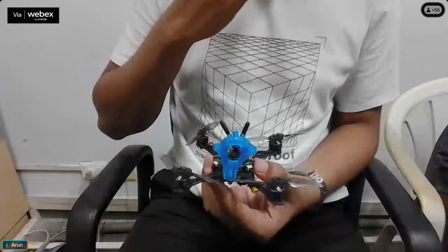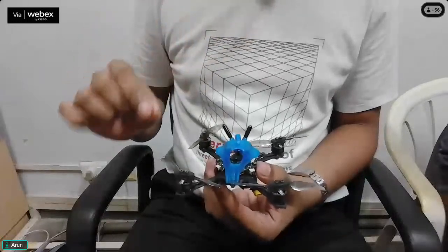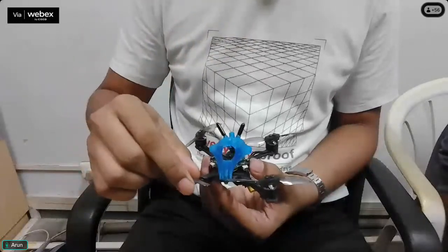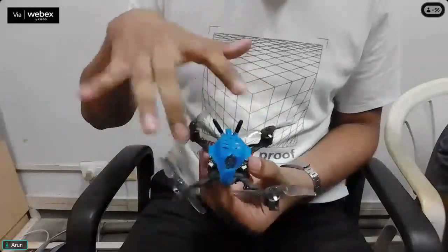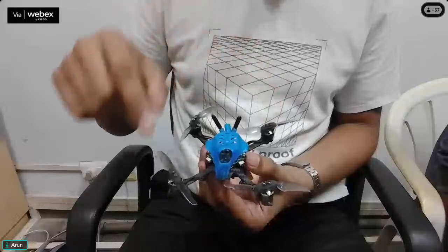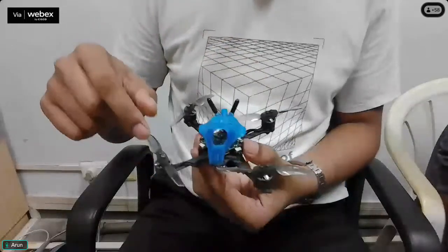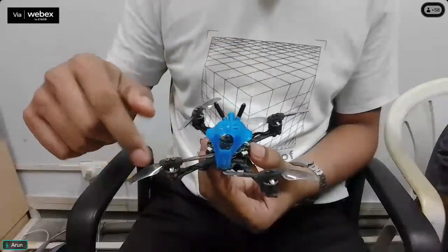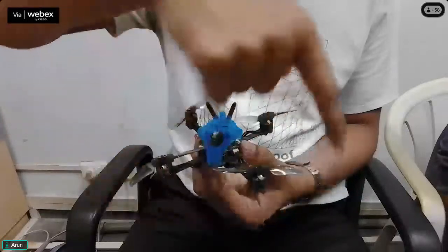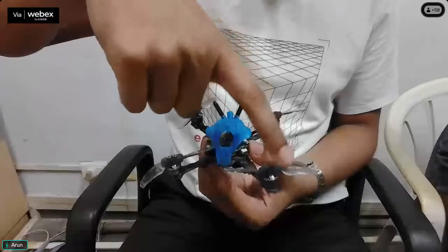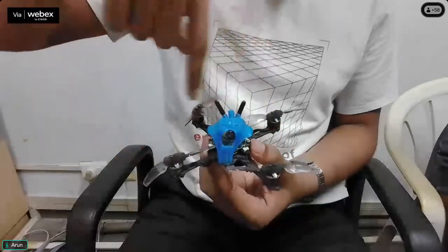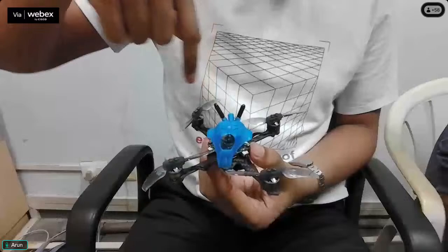Now one motion is remaining, which is yaw. What have we talked about for yaw? For yaw, diagonally opposite rotors have to rotate at the same speed. When you make these rotors rotate at the same speed, the torque will be like this. Or if you rotate these two at a higher speed than the other two, the torque will be like this.